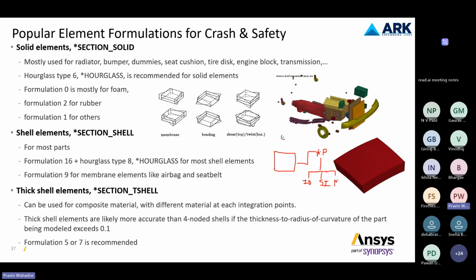So when we create any part, these are the important inputs we need to define. The section ID is nothing but it will tell you how the element looks, whether it is solid elements, shell elements, or a beam element. And the ID which is created for this particular section shell needs to be defined in the part, that is *PART.